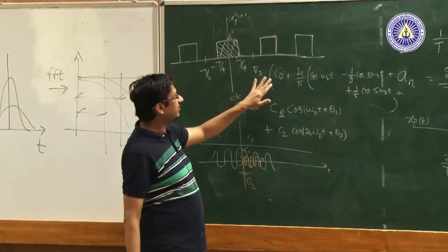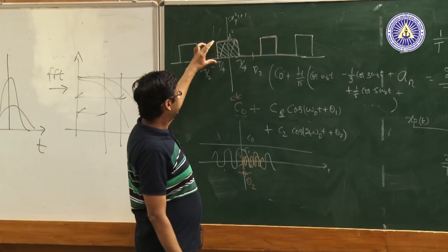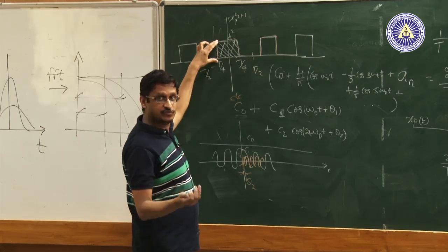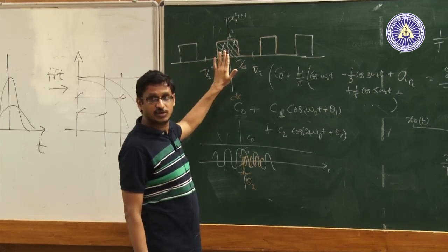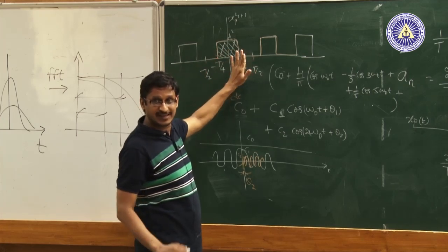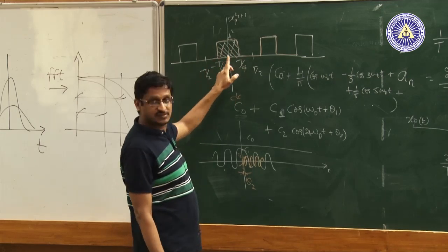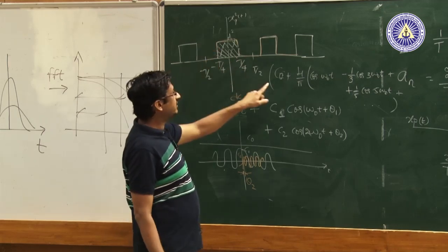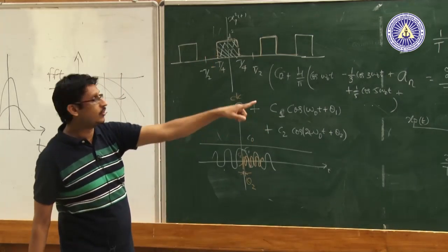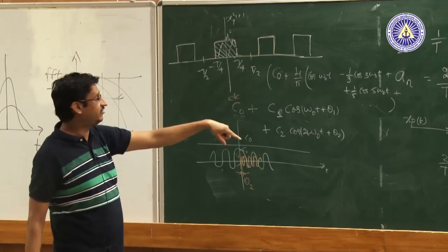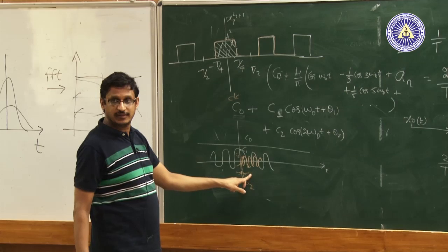What we mean here is that this signal has a non-zero average value, which is very clear, because for a signal to have an average value equal to 0, the integration should essentially go to 0, which means it should have both positive and negative parts which are equal, which should cancel with respect to each other. Because that is not happening for this signal, there is a non-zero average value, and then if you apply our Fourier series formulas for A n, B n and so on, you will also realize that you do not need cos 2 omega 0 t in this case.